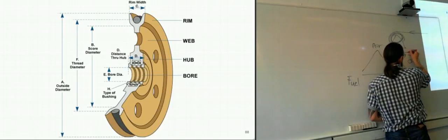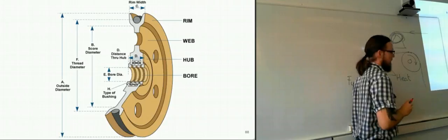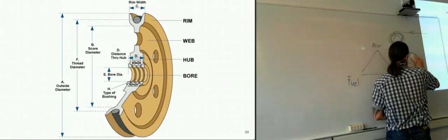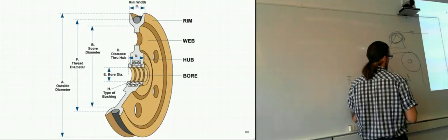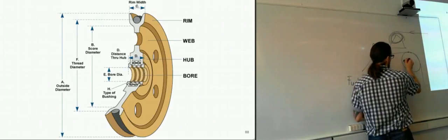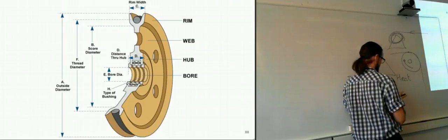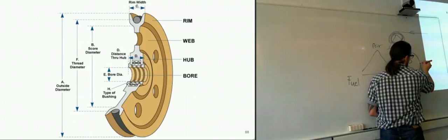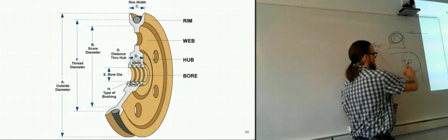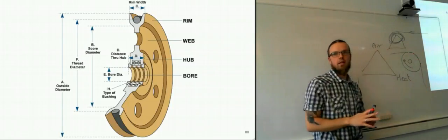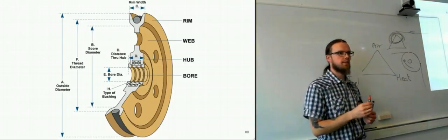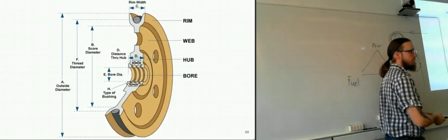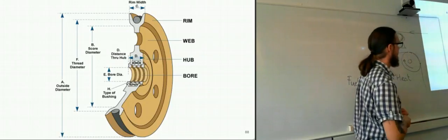So this point of the wire, as we rotate this one down here, this point of the wire up here will still be in contact with the same part of this disc that's rotating. So it's not being dragged across the steel of the disc, which means that we don't have this friction, we don't have the wear and tear, we don't have the heat being created.